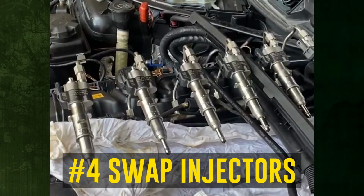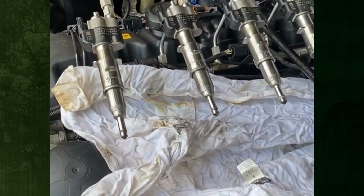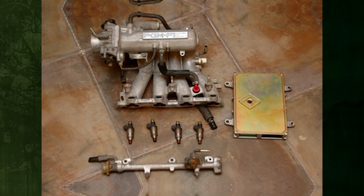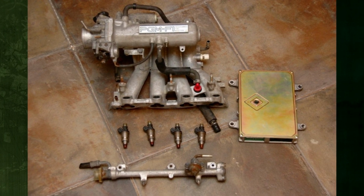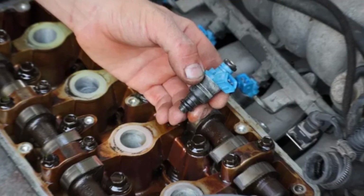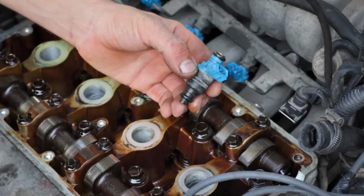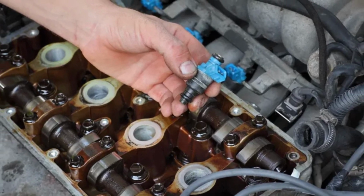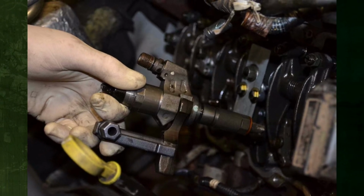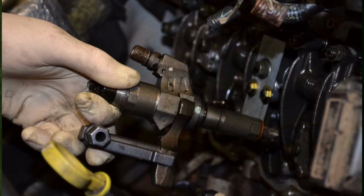Swap injectors. The engine's number 3 fuel injector should be replaced with an injector from any other cylinder if testing continues to yield conflicting results. Once the engine has run, check to see if the problematic DTC has shifted to the cylinder where the original injector was previously located, or if it has remained in the number 3 cylinder. In the event that cylinder number 3's problem continues, the injector circuit itself is called into question. Should the issue shift along with the injector's location, it is best to replace the offending injector.